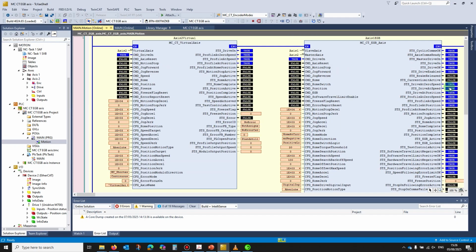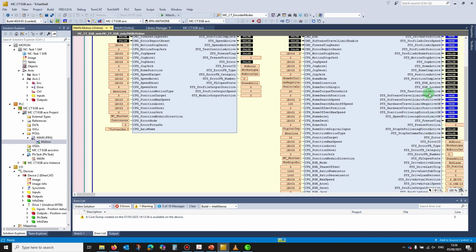So those are Boolean outputs, so it could be anything from telling us with a Boolean state, true or false, whether or not the drive is okay, whether we're at speed, at 0 speed, whether or not any of the particular references are active or not, or which one is active, which one has got control, things to do with hardware limits, freezing, which is analogous with MC Touch Probe. So freeze is like a Control Techniques terminology, but it basically means position capture of the axis.